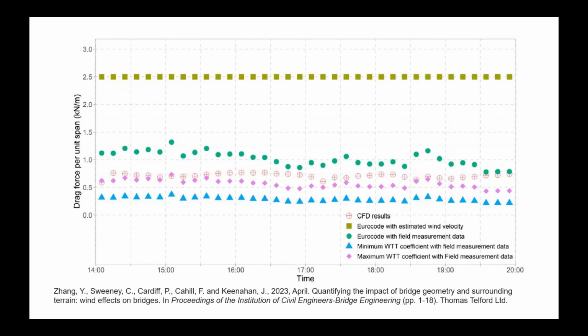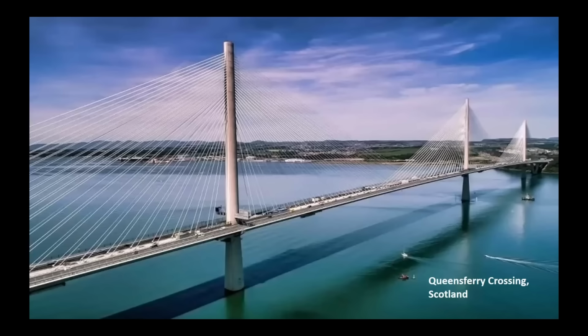There's quite a big difference between what the wind tunnels would report and then what our CFD simulations have found, and indeed different again to the sensors and what they can capture. So there's certainly a lot of room for further investigation to truly understand what we take as the true data. And the true data, of course, is the field measurements. And then how good an approximation are the wind tunnels, and how good an approximation can we get from the numerical simulations.